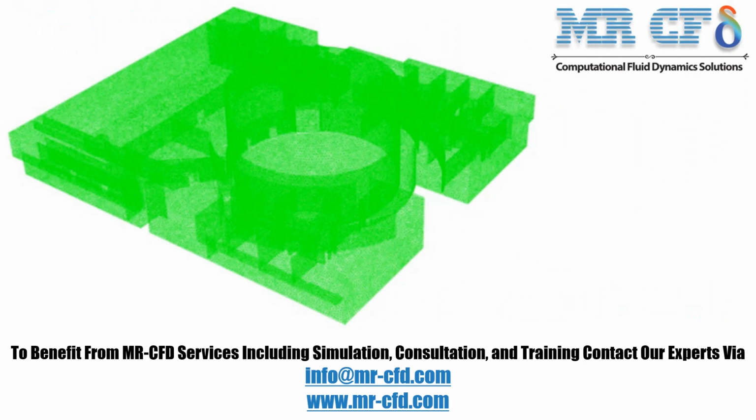The meshing of this model has been done using ANSYS Meshing software. The mesh type is unstructured and the total element number is equal to 2,496,105. The cells adjacent to the internal boundaries are smaller and more accurate.